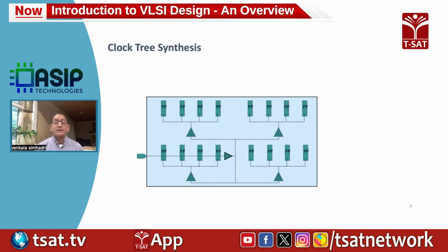You have to make sure that the clock insertion delay, the time it takes from the periphery to reach the flop, is within the limit when it reaches every flop in the design. I'm kind of simplifying things a little bit here.